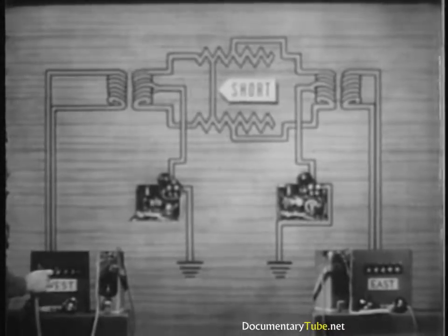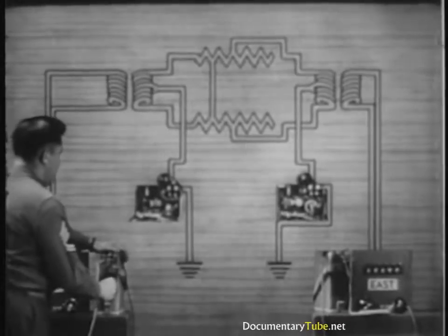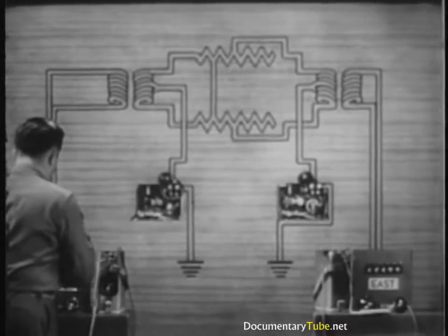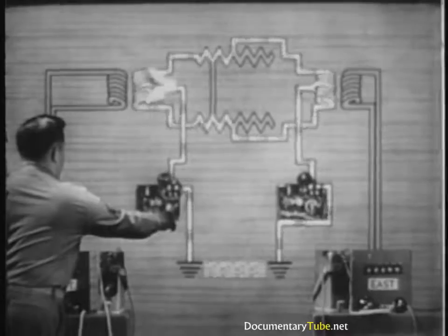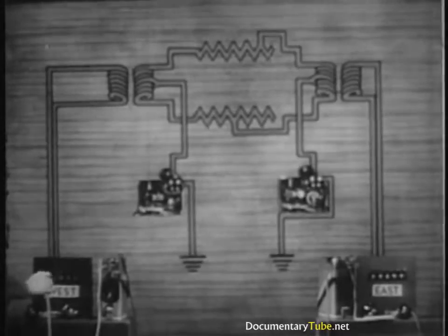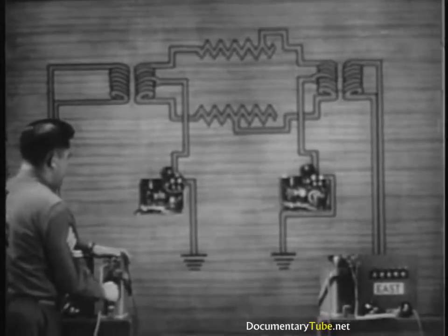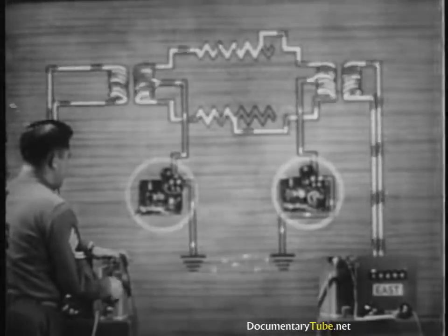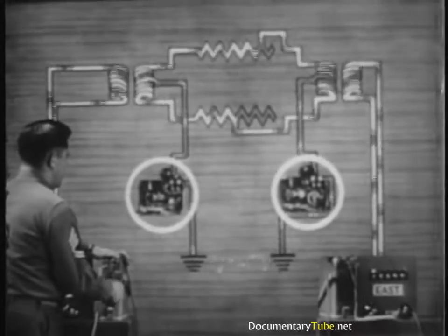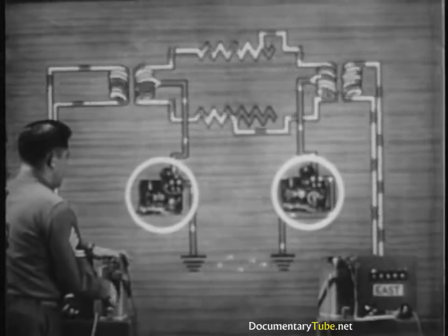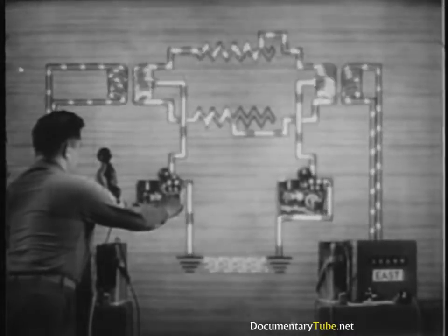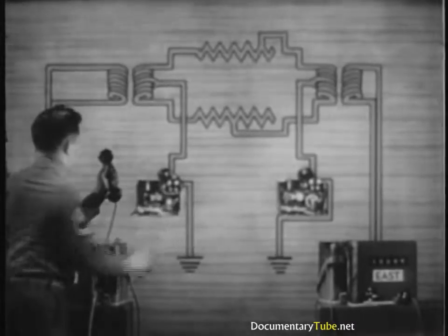When the line is shorted, the telephone channel's no good. But the telegraph channel's as good as ever. When the resistances of the two line wires become unbalanced, telephone current flows through the telegraph sets, but it's rarely strong enough to interfere with telegraph communication. The telegraph does interfere with the telephone, but not sufficiently to disrupt telephone communication.